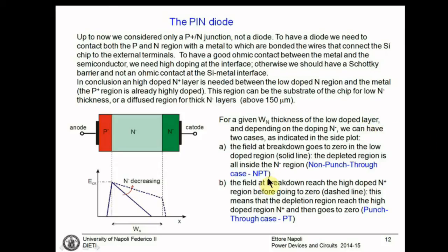However, this region here is not thin, it is quite thick. It is the substrate, maybe 100, 200 microns. It is shown here very thin for teaching purposes, because we want to see the active region, but this region is thick. This is not the case on the other end, that is very thin. This is a diffused region on the top of the surface.